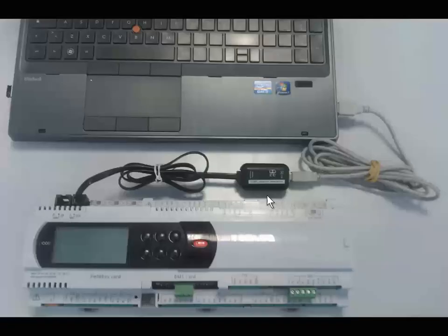You have to use a USB to RS485 converter. USB this side connected to any USB port, and on the other side RS485 to this terminal of the Pico. Don't confuse this terminal with the one on the left, because it is for a completely different purpose. So normally here there is the terminal, so disconnect the terminal and connect the converter to the PC.